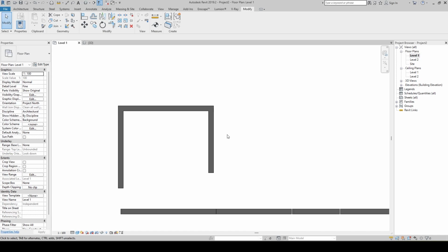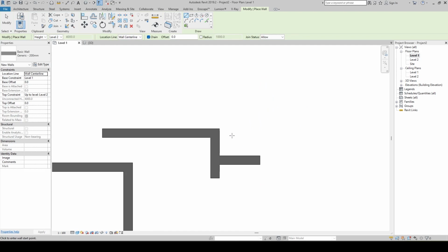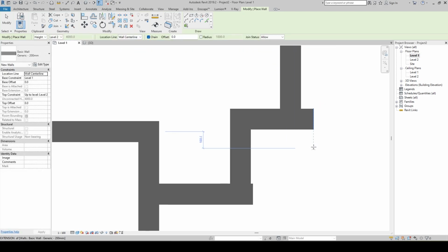That means, once again I'm explaining, you have taken one more wall here, extended this way, closing this way. Now once again I'm taking the wall, leaving some extra. Then here as well, I'll do WA somewhere here, closing. Then once again I'm closing this way. Now let us explore the trim option.